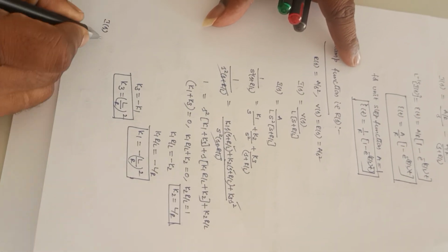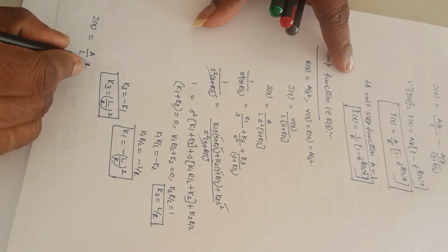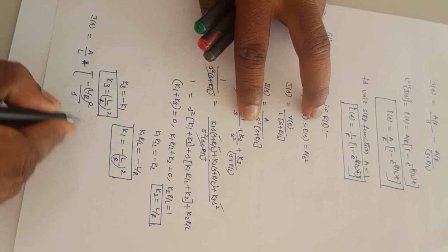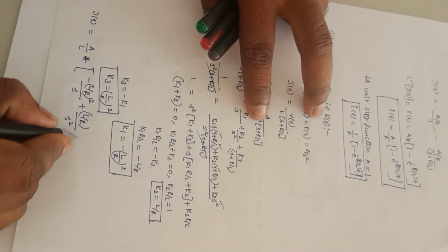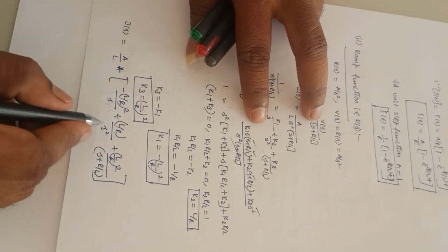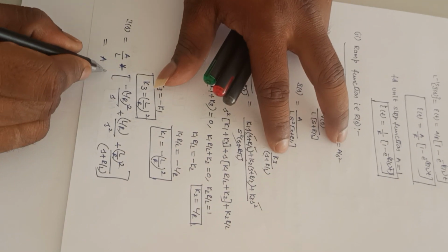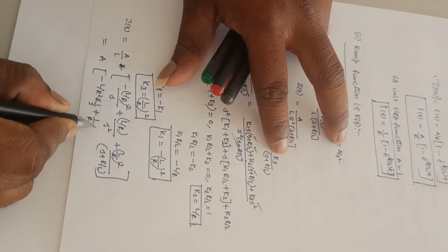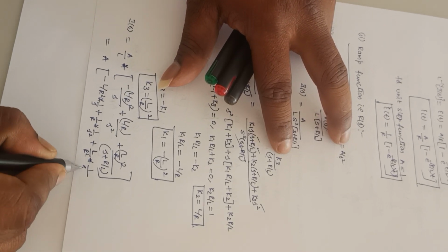So I can write I of s is equal to, take A by L as a common, A by L. So this term 1 by s square into s plus R by L is this one. So into, k1 is minus L by R whole square divided by s, plus k2 is L by R divided by s square, k3 plus L by R whole square divided by s plus R by L. Now if I take L in all these things, I will get A into minus L divided by R square into 1 by s plus 1 by R into 1 by s square plus L by R square into 1 by s plus R by L.